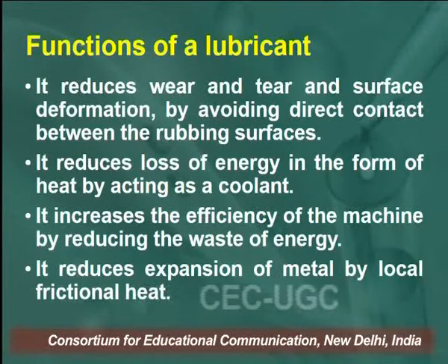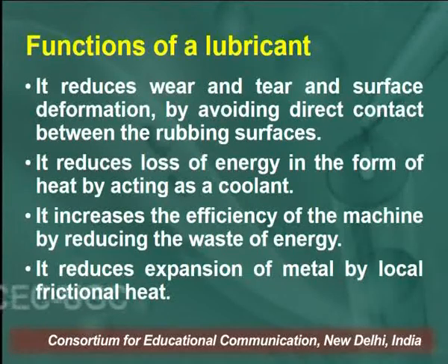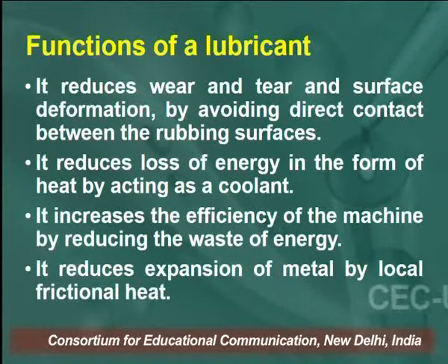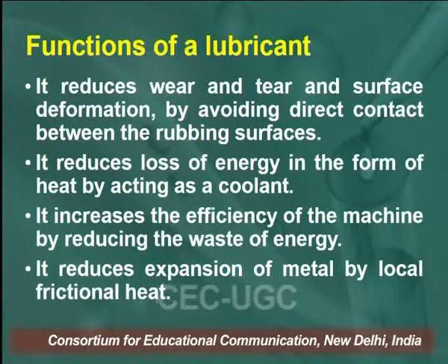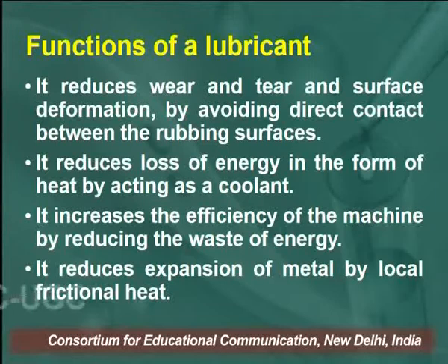It reduces wear and tear and surface deformation by avoiding direct contact between the rubbing surfaces. It reduces loss of energy in the form of heat by acting as a coolant. It increases the efficiency of the machine by reducing the waste of energy. It reduces expansion of metal by local frictional heat.